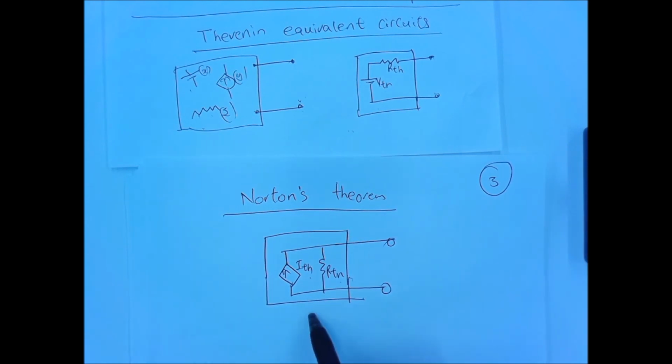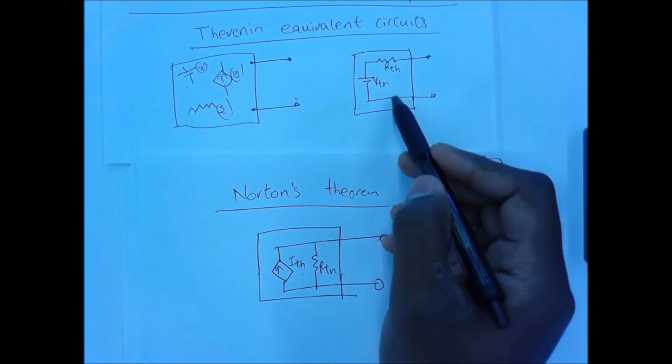Oh, so you judge the Thevenin and Norton based off of the resistance that's coming out of the box. And sometimes output resistance is very small, so you want to model it as a voltage source. That makes sense. Okay.